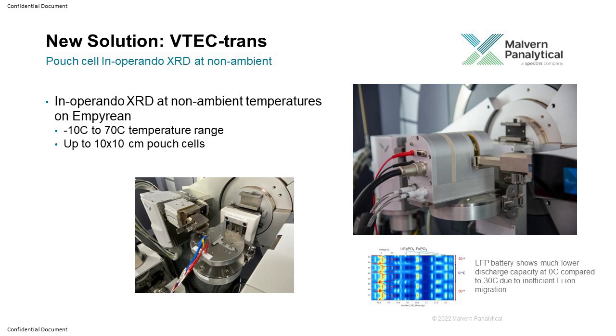But you also have to test what happens if the battery is heated to 50 degrees centigrade. When an EV is running, it is discharging, heat is produced and the battery can get heated up. So you have to see whether it behaves properly at higher or lower temperature.